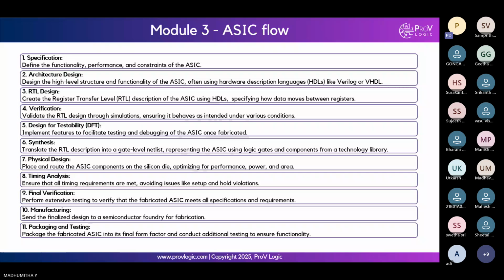Second thing is performance. Performance means timing. We discussed this 1 nanosecond example, right? If the client is saying I want my IC to operate at 1 gigahertz or 2 gigahertz, my design, which I am going to complete during physical design, must adhere to it. The sequential cells I'm using must be able to launch the data and capture the data in that 1 nanosecond time period. If it is going to take 1.1 nanosecond or 1.3 nanosecond, again it is a failure. That is called performance.